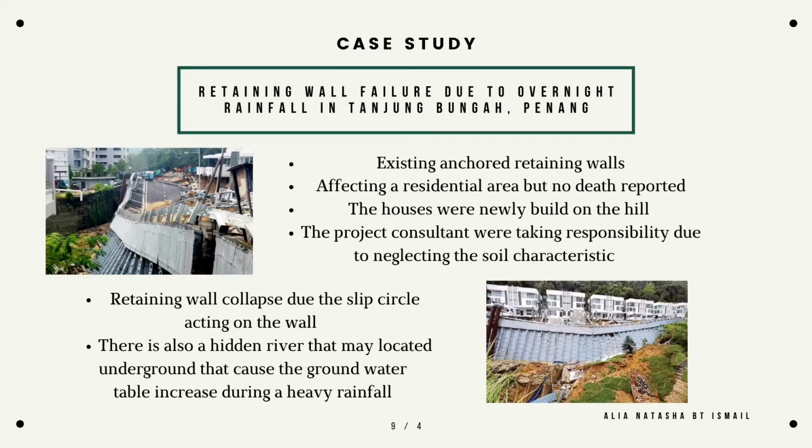For the case study, we chose the retaining wall that failed due to overnight rainfall in Tanjung Bungah, Penang. The existing retaining wall is the anchored retaining wall. This affected the residential area, but there was no death reported because the houses were newly built on the hill. The project consultant took responsibility for neglecting the soil characteristics on the site.